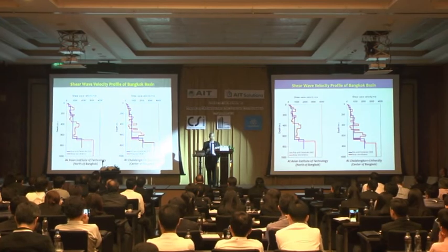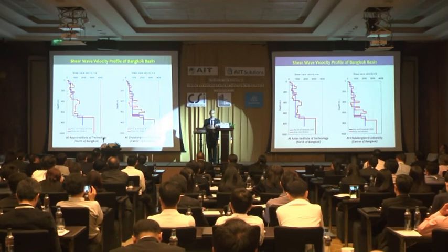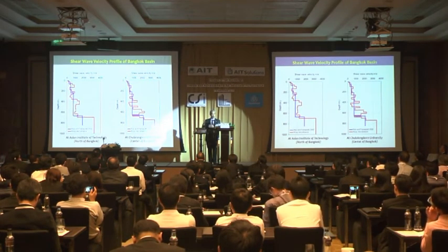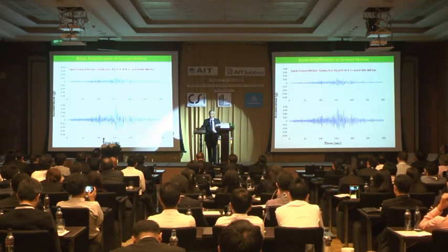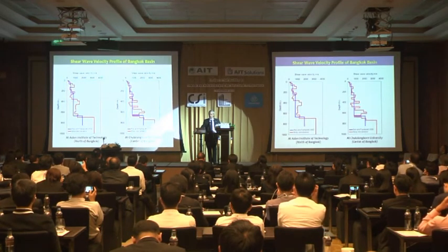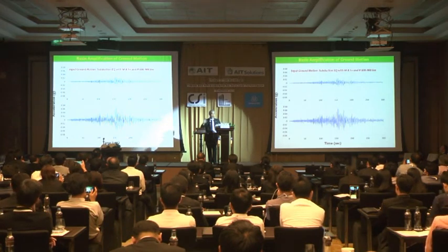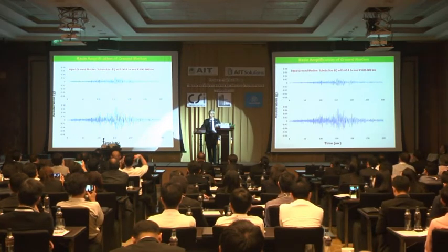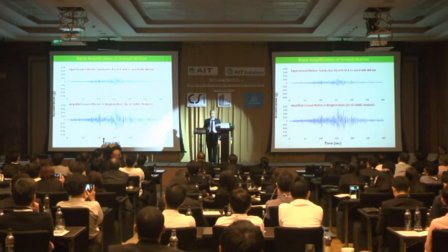We have the shear wave velocity profile. This is an important dynamic characteristic of the soil basin. We can make a model, like we make a model for a structure, but this is a model for the soil, to calculate how the basin responds to earthquake. From seismic hazard assessment, we can identify what the ground motion will look like from different sources, from different distances.